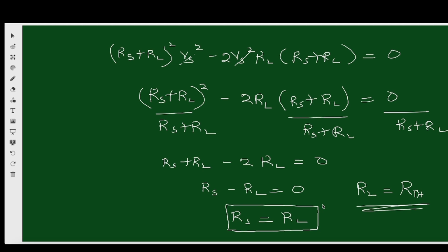A short circuit in this case, that is P is equals to I squared R. We just set R equals to 0 by shorting the network terminals. I explained to you in our previous lesson that if you are shorting a terminal, it means that the resistance there is 0. But if you are opening a terminal, it means that the resistance there is infinity. Current cannot move. The resistance there is infinity.